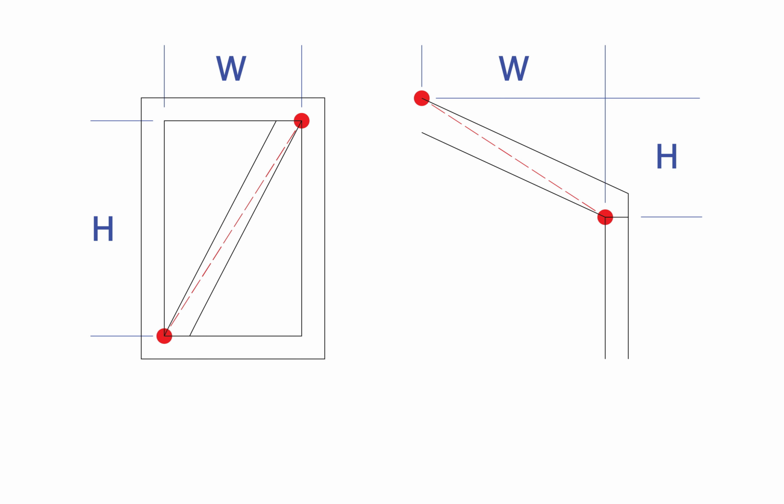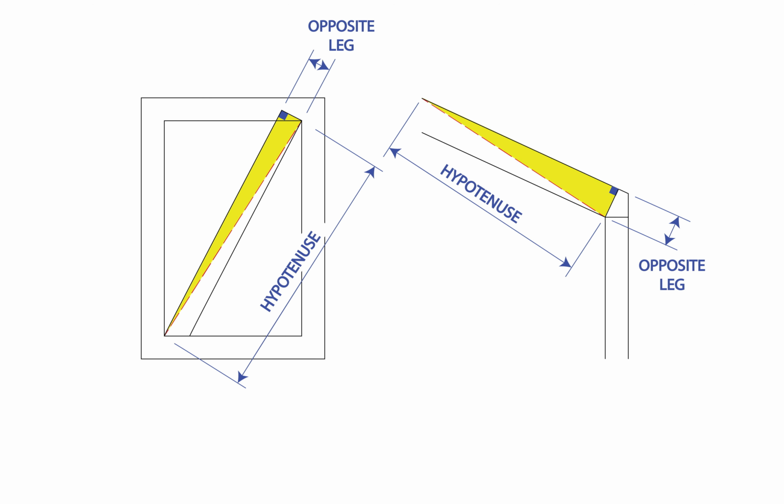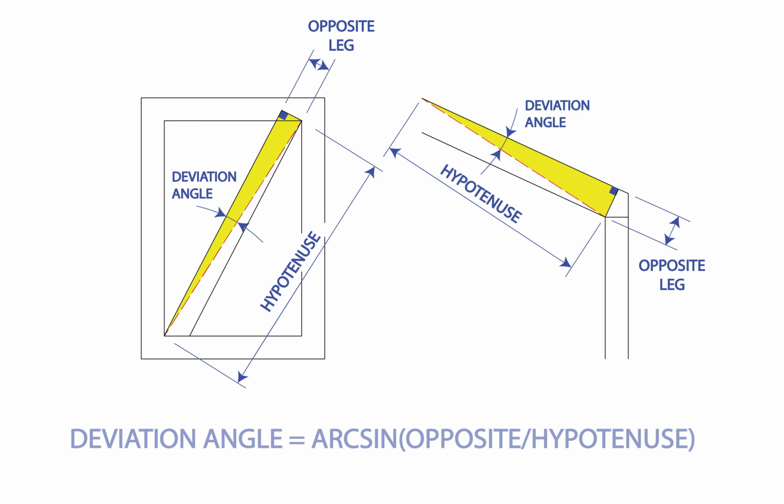This was a challenging operation in the days of hand drafting. Back then it relied on the use of a compass, a ruler, and a rudimentary knowledge of what mathematicians call Thales' theorem. All most of us knew was it allowed us to position two parallel sides of a board accurately in space the first time and without guesswork. It is true that one can simply draft these lines in Revit to recreate the hand-drawn solution. But if one is working in the family environment, it becomes necessary to have a deeper understanding that permits the relationship to flex in this parametric environment.